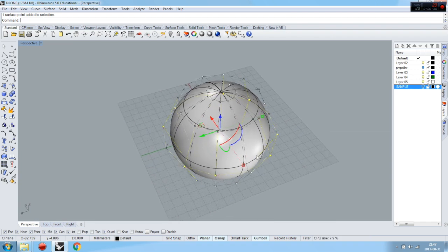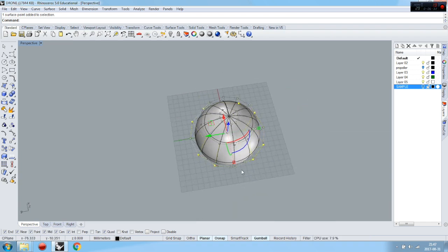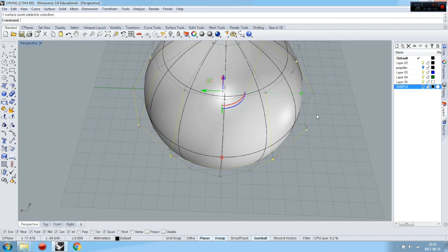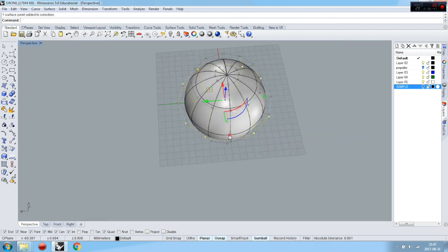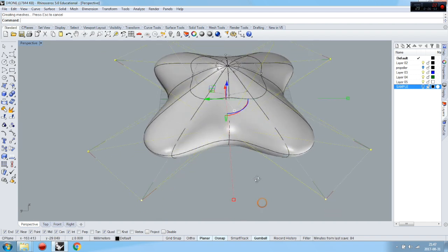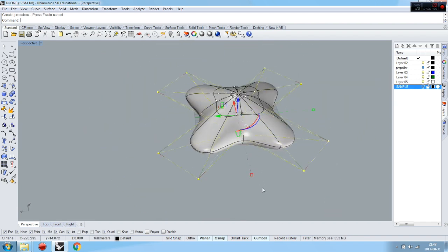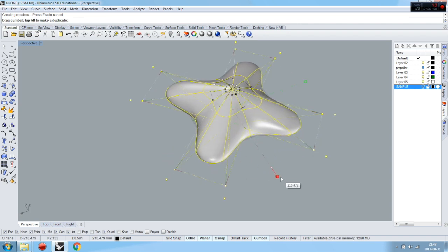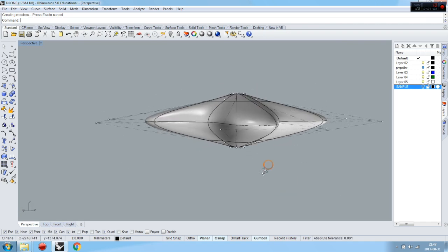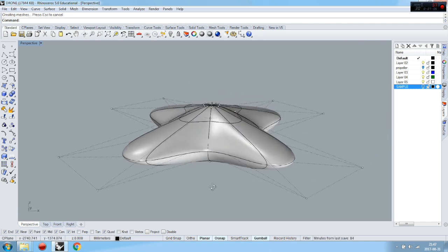You're going to scale it proportionally with Shift pressed. So if you grab this red triangle square here, or this red green square here, you're going to scale it, but with Shift you do it proportionally, you see. And this is what we actually love about Rhino very much. Not many people use this stuff because they're really not into doing that. I don't know why, but this is great.